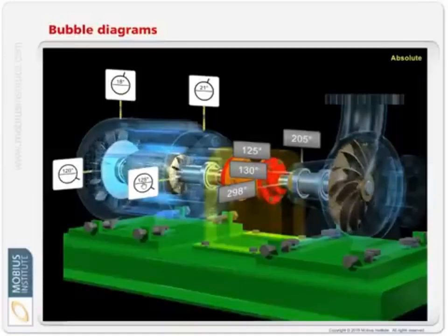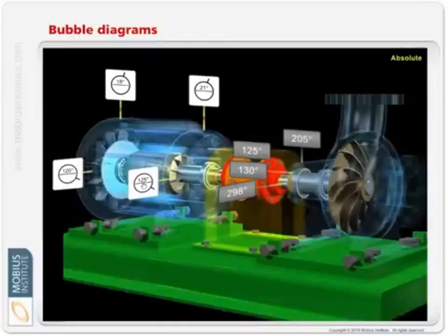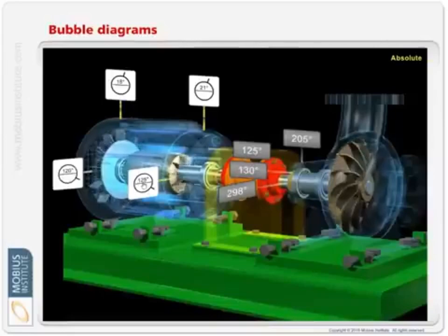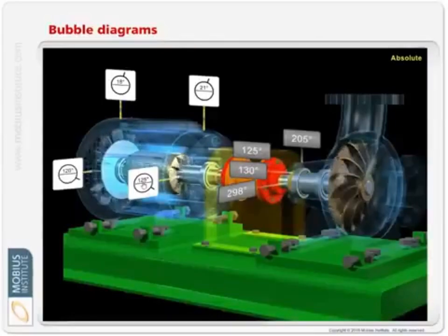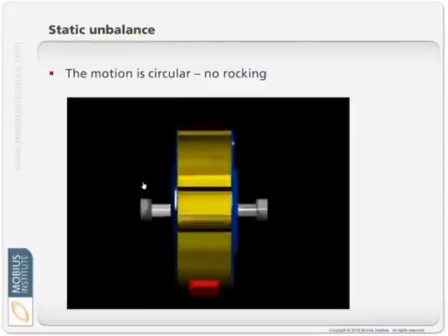and with certain fault conditions to tell, hey, is it misalignment, is it out of balance, is it resonance, is it looseness? They're just these faults that can kind of look the same in the spectrum. This phase analysis helps us pinpoint exactly what's wrong with the machine. So we only need to do this if we're really not sure what's wrong with the machine, but we're pretty sure something's wrong. So it's a really useful tool.